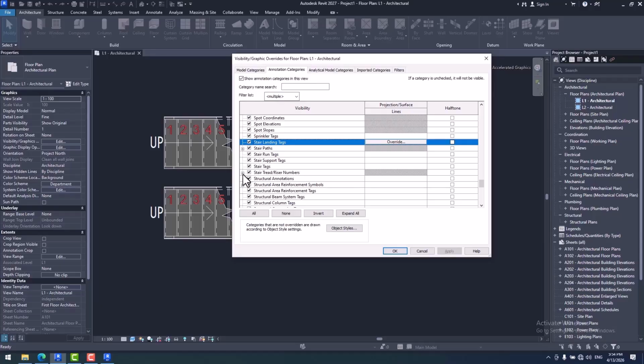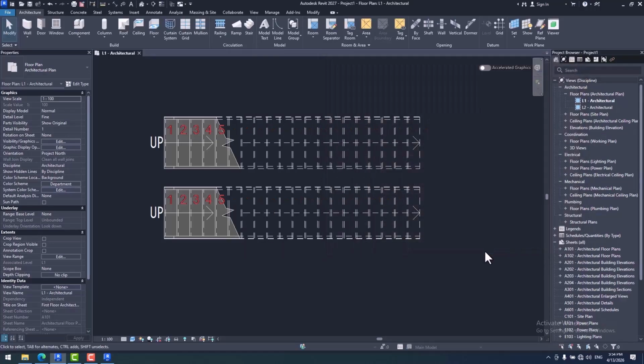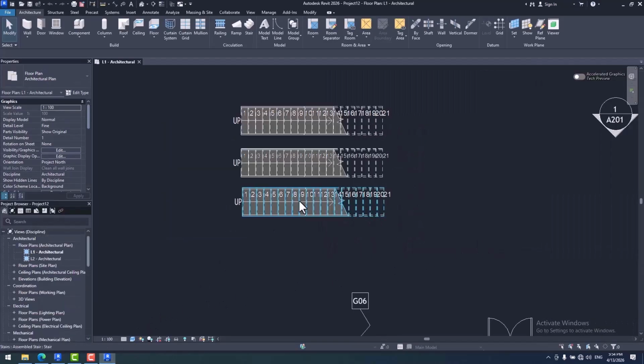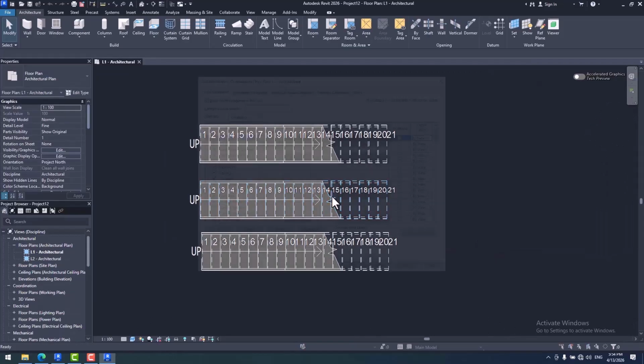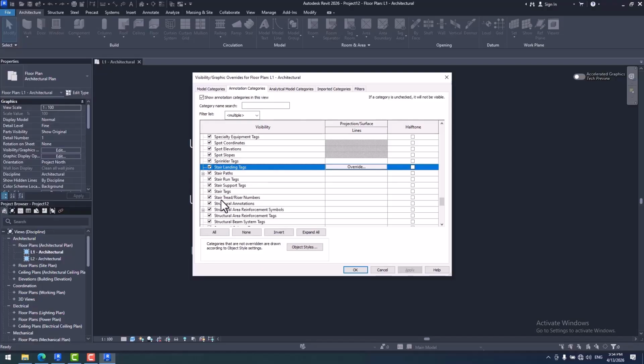Now, here we can also control the numbers on both sides of the cut mark, guys. We can, for example, enable or disable them. For example, I'm going to turn off the numbers above the cut mark. But again, guys, remember, this wasn't a thing in prior versions of Revit. Take a look at this in Revit 26. Stair Tread Rise and Number basically does not have any subcategories.